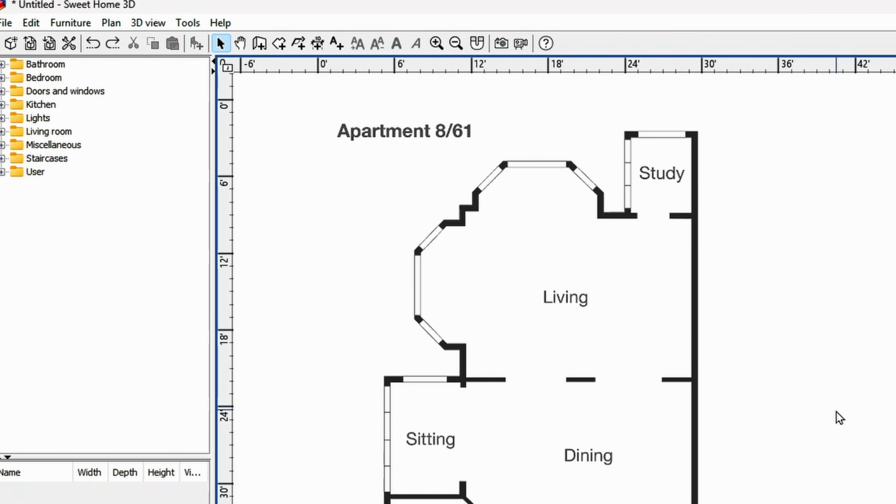As the next step, create the walls using the imported floor plan. Go to the toolbar and click Create Walls button. Then move to one of the corners, left-click with your mouse, and start drawing a wall.